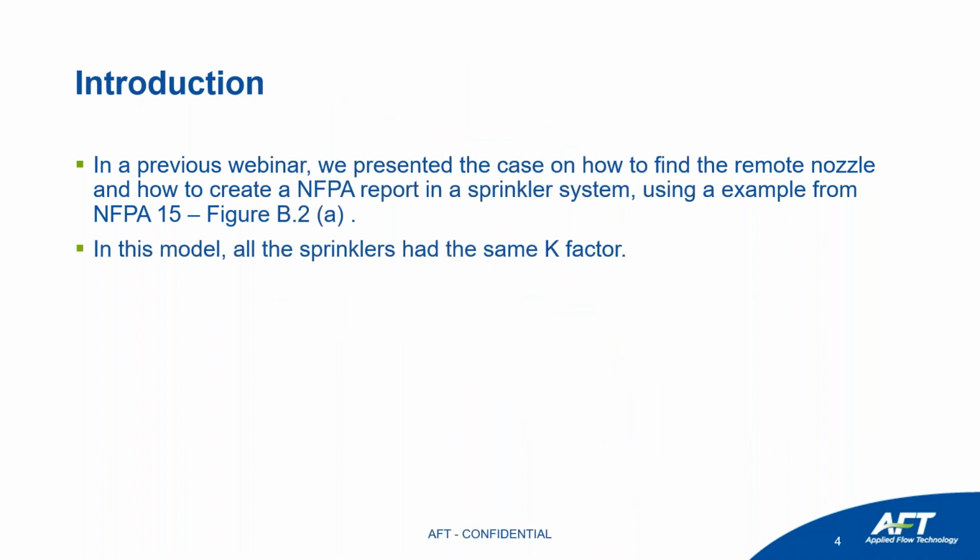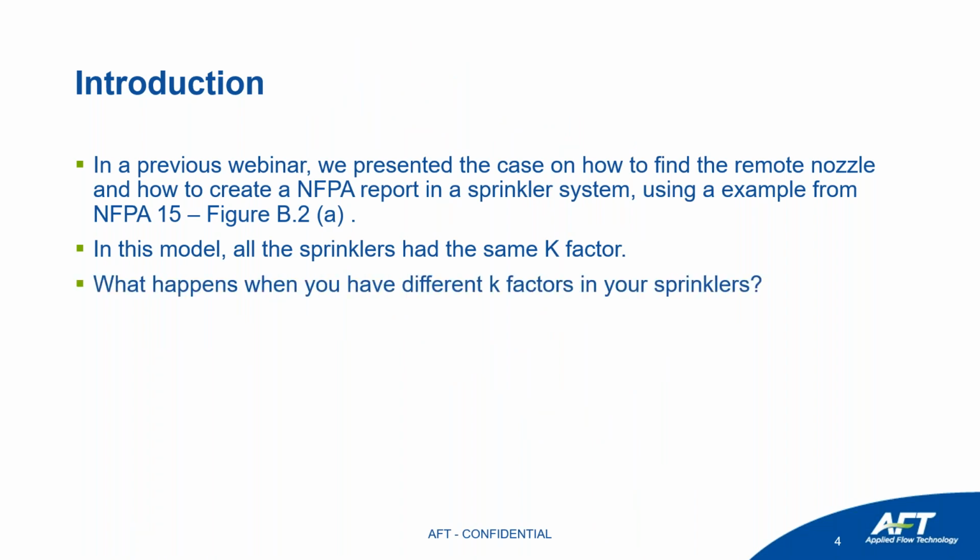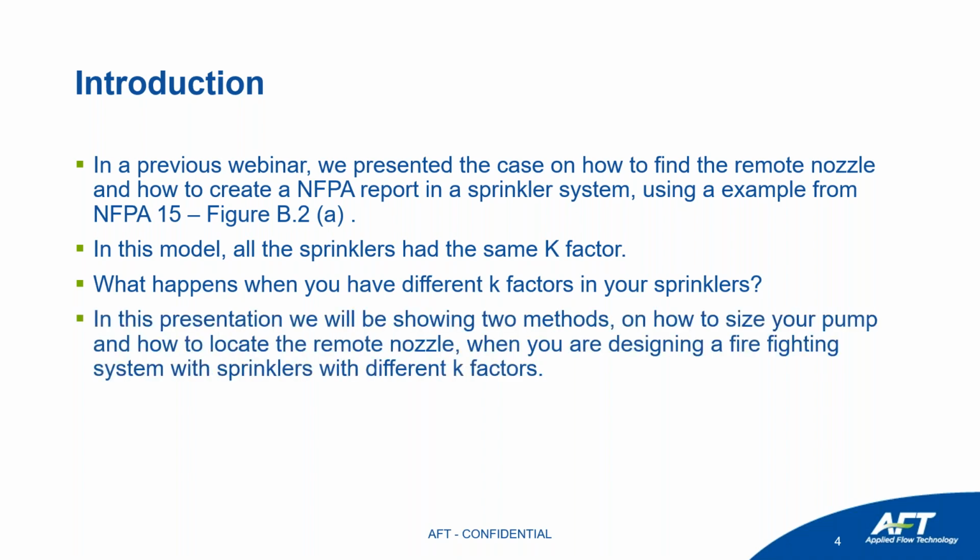In this model, all the sprinklers had the same K factor. But what happens when you have different K factors in your sprinklers? In this presentation, as I mentioned before, we'll be showing two methods on how to size your pump and how to locate the remote nozzle when you are designing a firefighting system with sprinklers with different K factors.